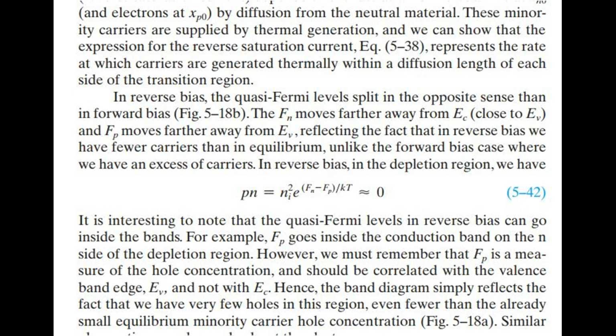In reverse bias, the quasi-Fermi levels split in the opposite sense than in forward bias, Fig 5-18b. The Fn moves farther away from EC, close to EV, and Fp moves farther away from EV, reflecting the fact that in reverse bias we have fewer carriers than in equilibrium, unlike the forward bias case where we have an excess of carriers. In reverse bias, in the depletion region, we have...